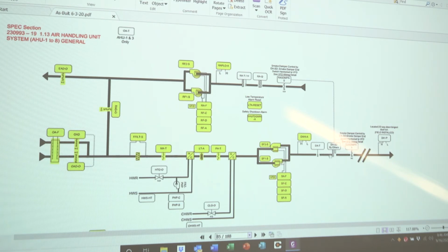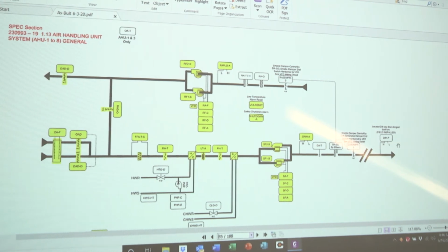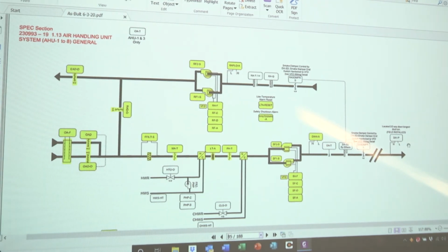You go through your smoke dampers. You have a pressure switch, your pressure control that is operating the supply fan speed, located 2/3 down the duct stream. So that's within the building. I think you will wind up on the 3rd floor on most of these units. This is the pressure switch that's actually controlling the speed that these fans are operating at. Supply fans, safety switch, discharge air temperature, smoke dampers with end switches controlled by your pressure switch.